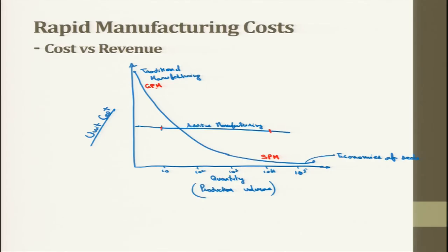In a bolt maker, the billet goes in, forming happens first and the hexagonal bar is produced, then it is cut, threading happens, and the bolt is produced in one go. So we use special purpose machines here, and the unit cost is reduced. However, the fixed cost is higher for special purpose machines, but the overall cost per unit is reduced.